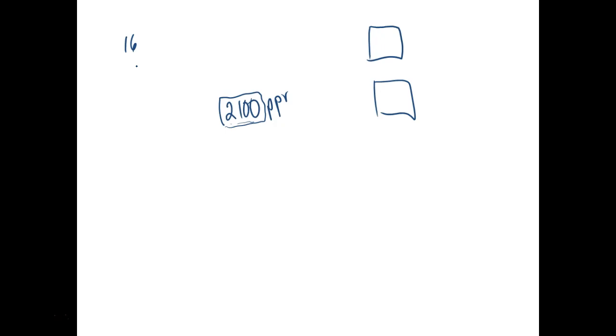And then if we decrease the speed, we increase the torque. So what they're doing here is they're dividing the speed by 131.25. Does that make sense? So that means my output shaft is only turning this divided by 131.25.